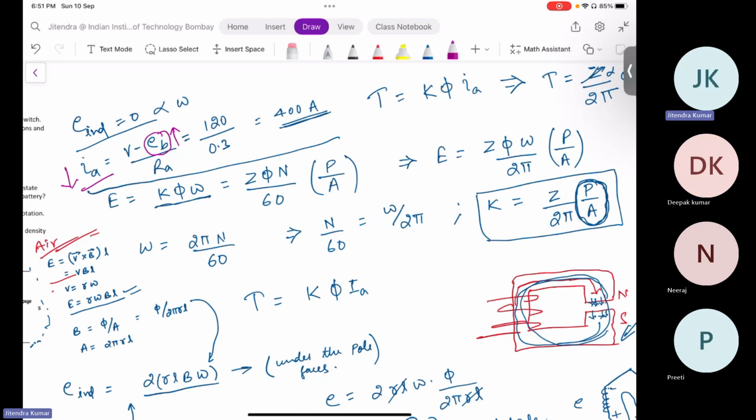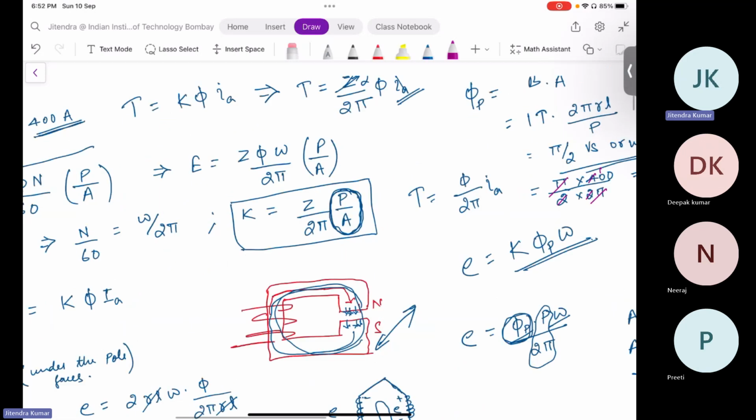That is why at starting, high torque is required. This is a very important point. At start, and even in the characteristics of the machine, you will see the starting torque requirement is very high. As you apply this amount of torque, your rotor starts rotating and the torque requirement will reduce. That's a very important point I wanted to emphasize. So this is what will happen.